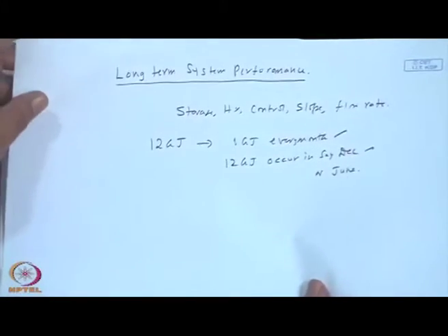So, not only the quantum of the load, but its distribution also plays an important role. Sometimes it may be fortunate for us, in the sense that if the demand in general follows the solar radiation, in other words, I have a higher demand in summer and lower demand in winter, then you will have a better performance index rather than the other way around.